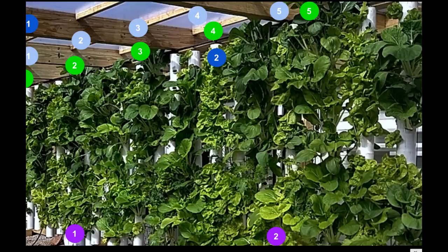Typically they come in AC, so if they're AC, we want to probably put them on a controller, because then you want to turn that on and off, because the way it works, if you have direct DC loads, they can be connected directly off the photovoltaic panels, and therefore you don't need any control on that. That just comes directly from the DC. But if you have an AC load, you need to have gone through an inverter or something, so you would need to turn that on and off. Just the sunlight coming up and down would not do, because the inverter would be on 24/7.